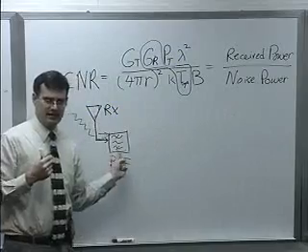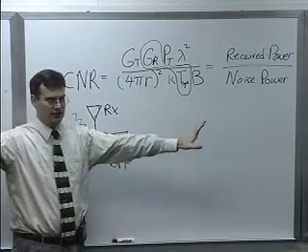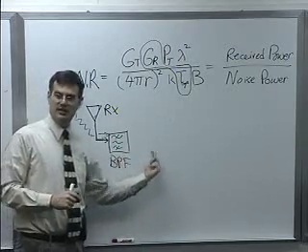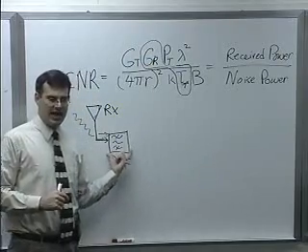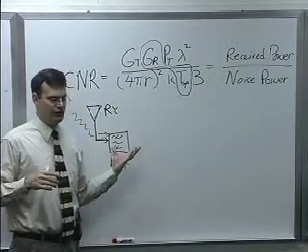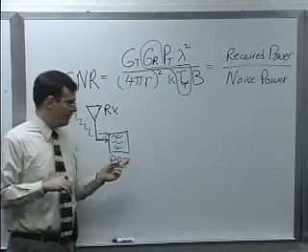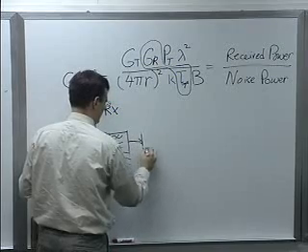This is for knocking out any out-of-band interference. Even if you're going to filter it through subsequent stages of bandpass filtering later in the RF chain, it's important to knock out any nearby interferers that could possibly be leaking through your antennas, because the next stage is going to be that low noise amplifier.